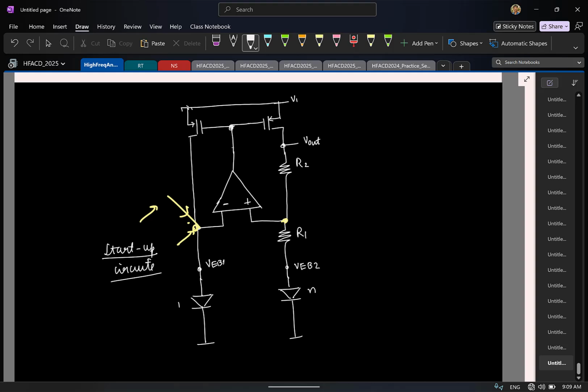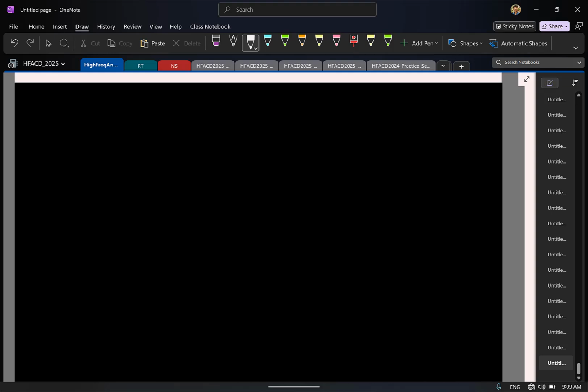Okay, cool. So that's majorly about band gap reference. So now you know how to design an on-chip voltage reference. So you can get a reference voltage Vref. And remember, our goal is to make sure that we are able to provide DC supply to the rest of your circuits. So now let us say this Vref is equal to the VDD of your chip.